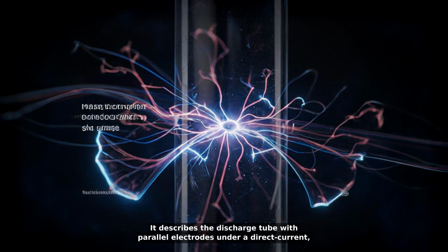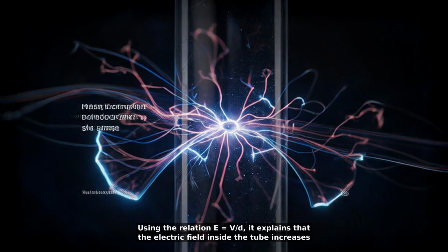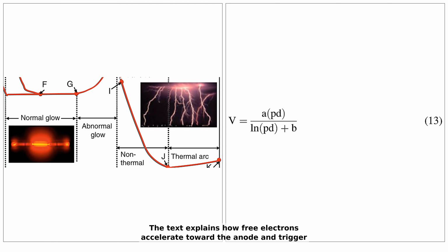It describes the discharge tube with parallel electrodes under a direct current, DC, voltage. Using the relation E = V/D, it explains that the electric field inside the tube increases with applied voltage V and decreases with electrode spacing D. For narration, this relationship matters because it connects the hardware geometry directly to the conditions required for breakdown and sustained ionization. The text explains how free electrons accelerate toward the anode and trigger further ionization through collisions, forming an avalanche.